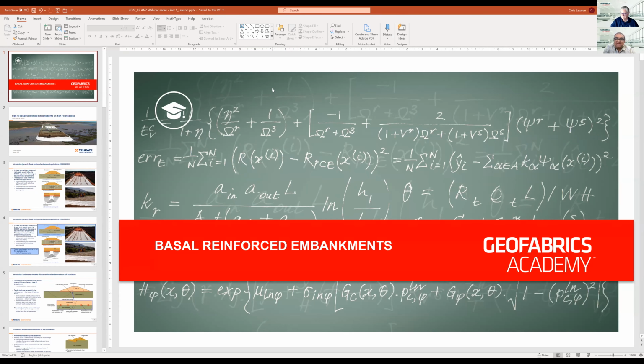The first question is, Chris, do geogrids need to apply with a separator geotextile, or arching effect can be relied upon? I think generally for embankments on soft soils, you don't need a separator with a geogrid. You just use the geogrid by itself,